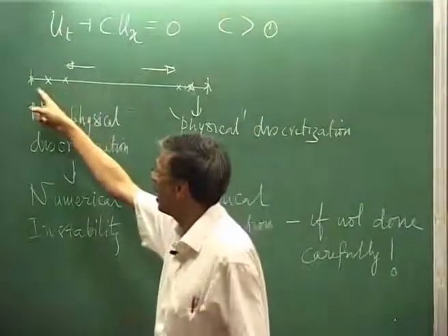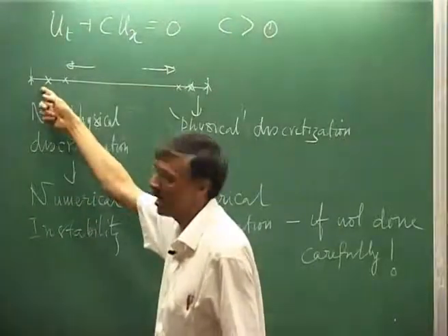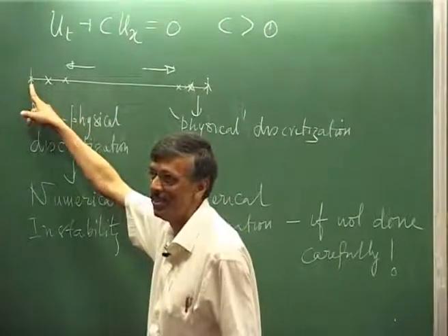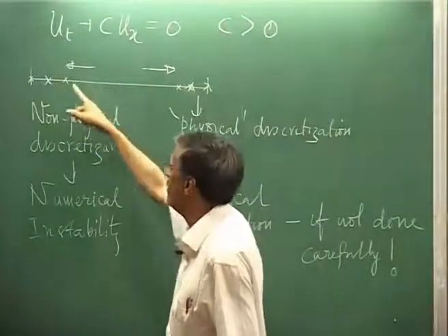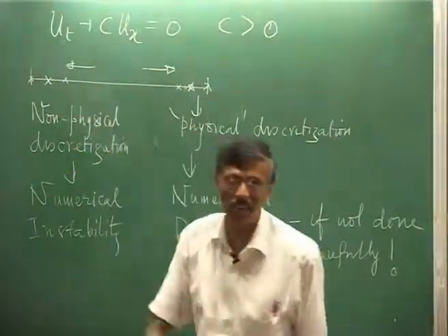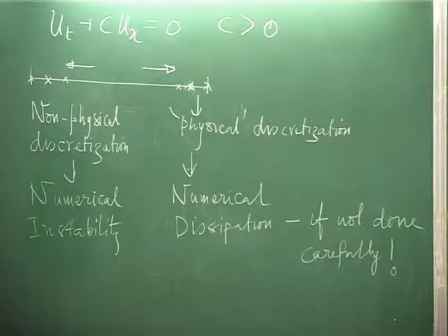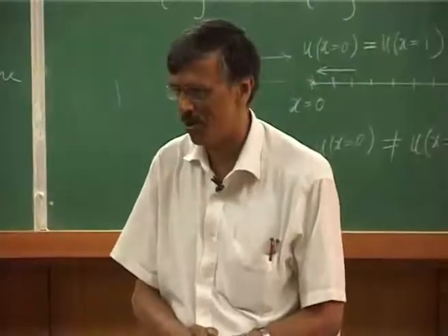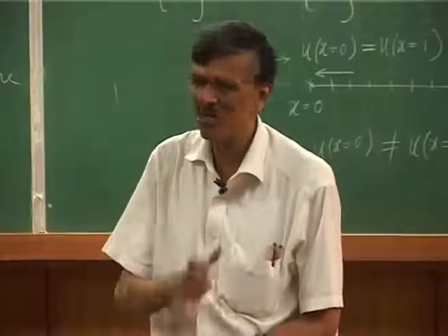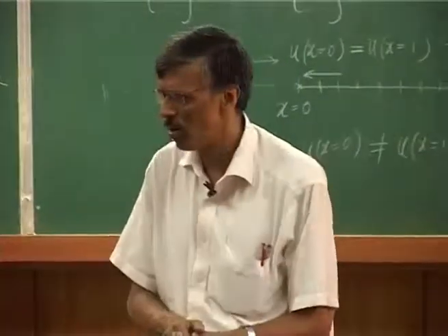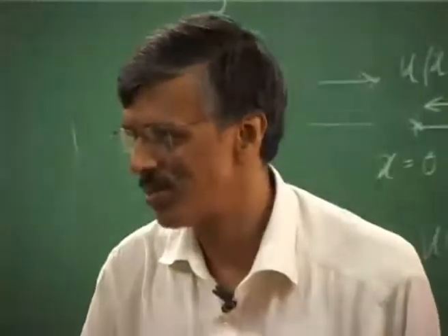The error is going to grow here, but it is also convecting. So after a few time steps, the error which was here will be inside, beyond this third point, and once it is inside, it is not violating the physical direction. This is actually a tragedy of computing, because people do this, then they go back and say, look, I am doing direct numerical simulation.